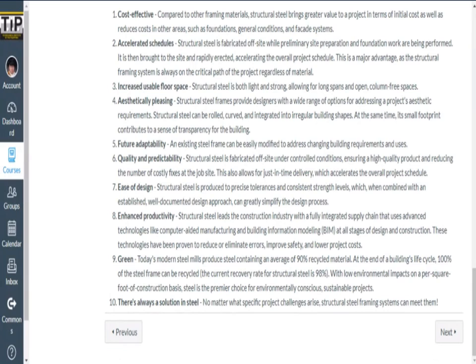So steel, on the other hand, can be used because we can assume that its behavior in tension and compression are pretty much the same. So we can use them as bracing. So if you actually read the list of structural systems for earthquake, no, in I forgot what table is that in NSCP, but it is in section 208. The list of the structural systems for steel is a lot longer than that of concrete.